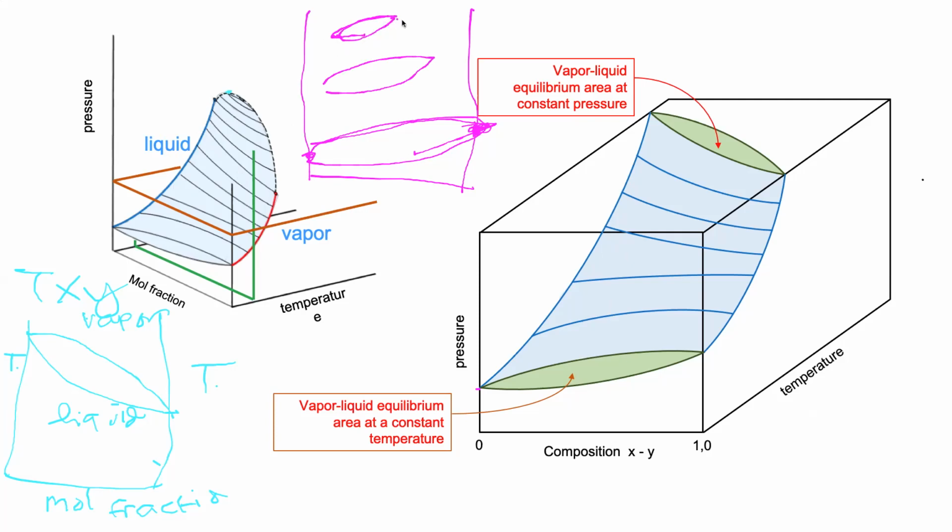So that means at higher pressure, it's not possible for us to go beyond this curve, and then it's not possible to get 100%. So that's why in the distillation, it is easier for us to do it at atmospheric pressure, at low pressure.